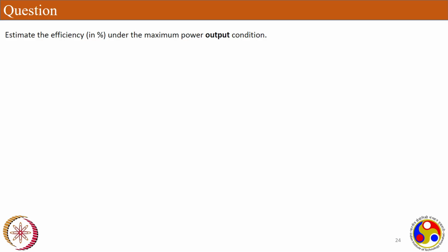So when you buy a motor, there will be nameplate details. That output power is the shaft power only. Do not get confused. You have to remember that your shaft power is the output power. That is the useful power, because the shaft is what you directly connect your load to. Whatever power is available at the shaft end can be completely utilized by your load.